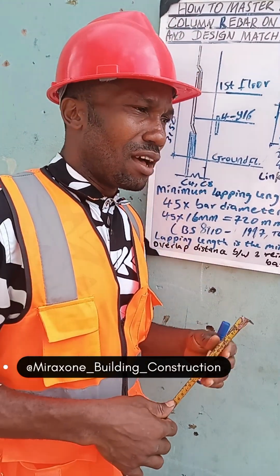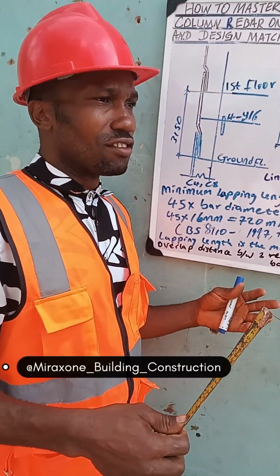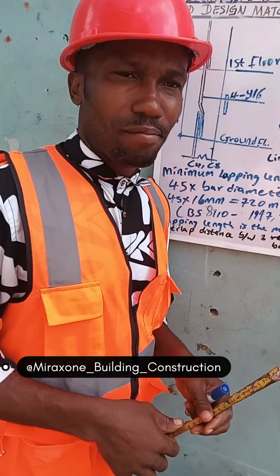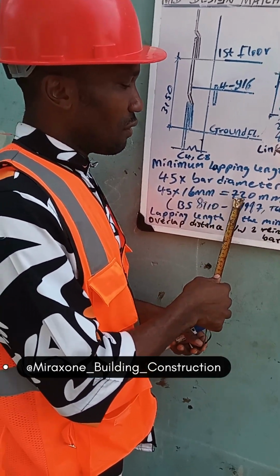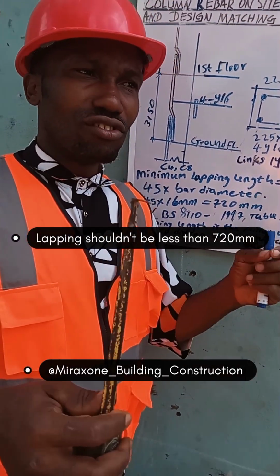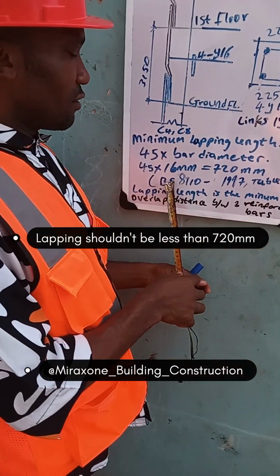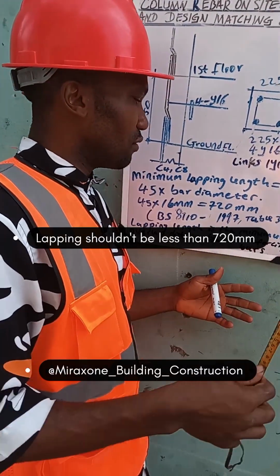But after much verification and calculation, I decided to use 45 times the bar diameter. That is 45 times 16 mm, which is equal to 720 millimeter. The lapping length should not be less than 720 millimeter. That's what I'm using. You should know that that's the British code, BS 8110.